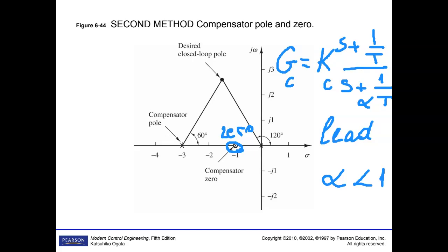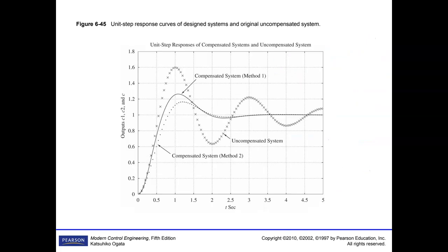However, you can see that you are going to add 1 zero here and one pole over there. The pole is far away from the origin, but the angle condition should be satisfied, and you already obtained for the home assignment that we are also adding a pole here. As long as you add a 0 and pole, your system becomes very, let's say, stiff, and the original waveform was this, and we improved that one.